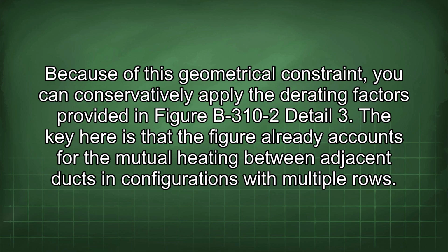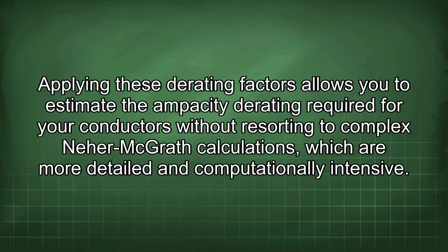The key here is that the figure already accounts for the mutual heating between adjacent ducts and configurations with multiple rows. Applying these derating factors allows you to estimate the ampacity derating required for your conductors without resorting to complex Neher-McGrath calculations, which are more detailed and computationally intensive.